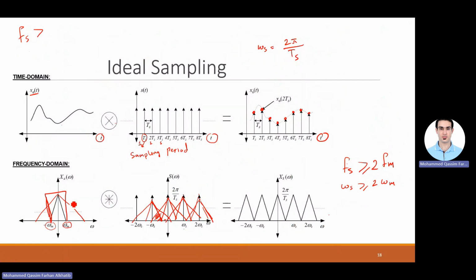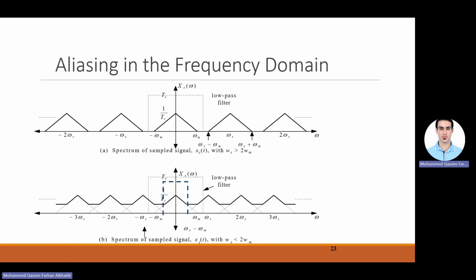You heard of cutoff frequency? Electronics, huh? Basically, after the cutoff frequency, the signal will be 0. So you apply a filter with a cutoff frequency equal to half the sampling frequency, the Nyquist frequency. So I will make sure that with sampling, I will not have aliasing. So I'll get something as close to this.